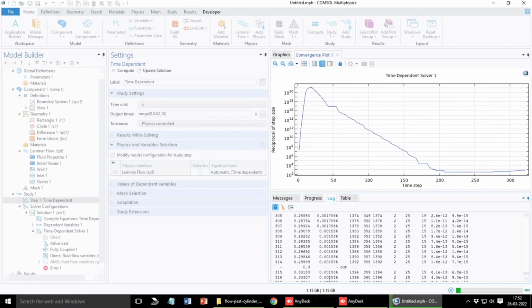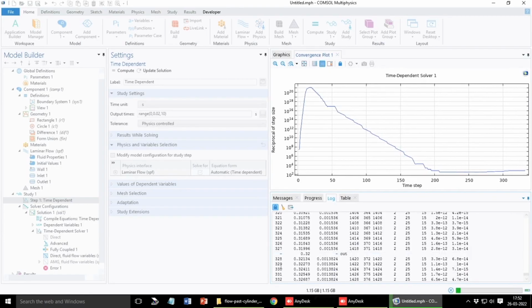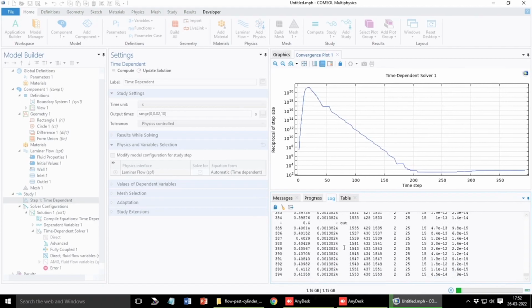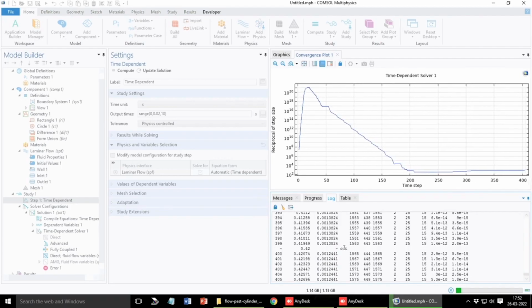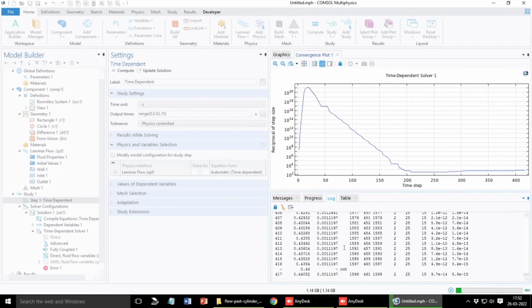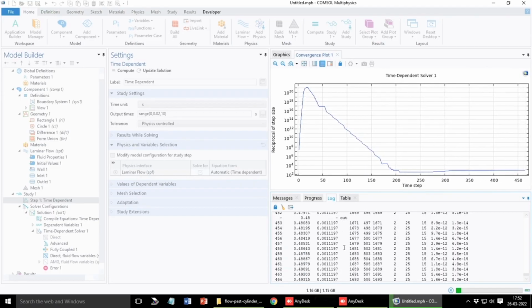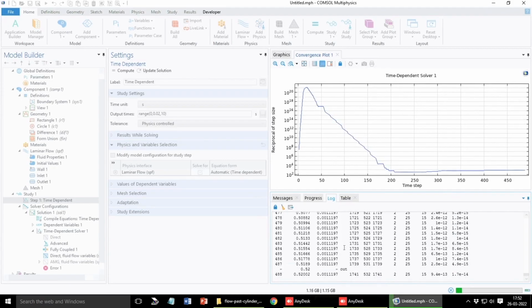It will continue to log other results, but it will stay at that point, and you see that these are the points, 0.32, where the software is saving the result, since it is a user defined time interval, right. Accordingly, the calculations are proceeding, and we have given time up to 10 seconds so that adequate vortex formations, or vortex formation transitions, can also be explored.